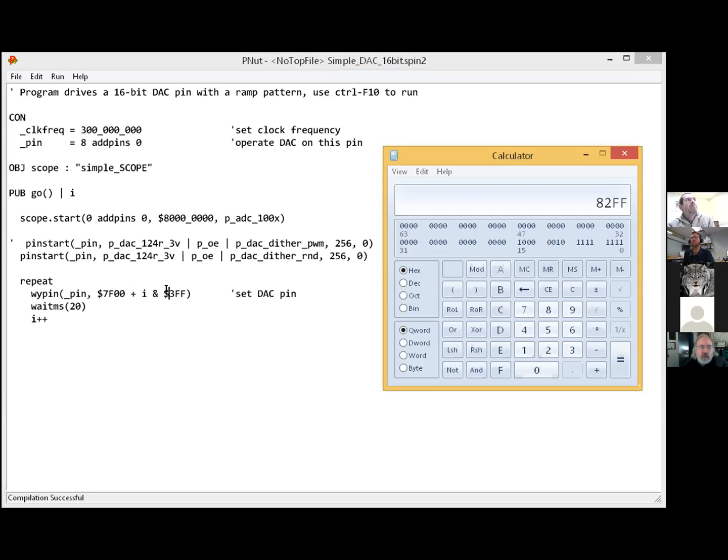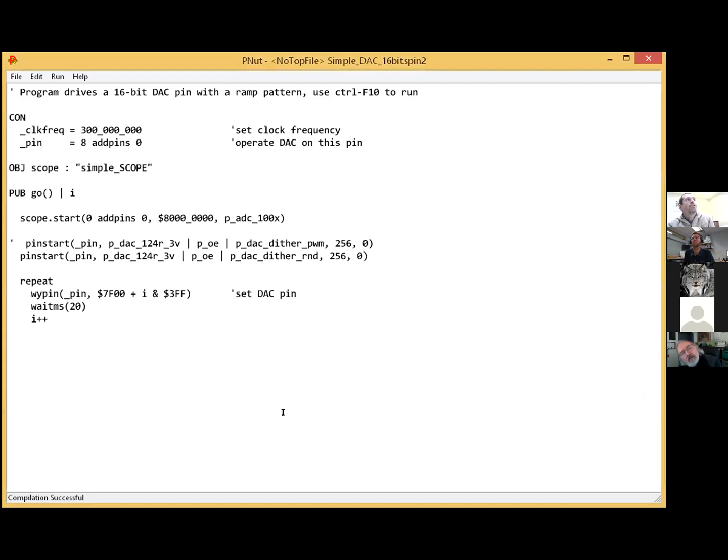And see, I could make this. You've got, I'm missing it, it looks like you're limiting I to 10 bits. And then you're adding that resultant value to 7F, which is like a coarse offset to get us into the range of the ADC.